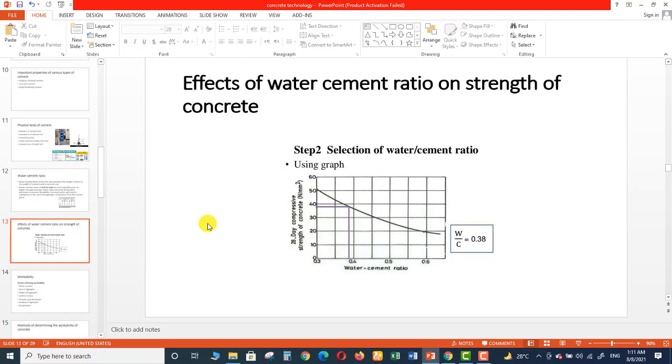As we previously discussed, that is the same thing. According to the water cement ratio law, the strength of concrete only depends upon the quantity of water used in workable concrete mix and is quite independent of the proportion of cement and aggregate. There is a law which we call the water cement ratio law, which was introduced by Abrams in 1918. That law says that with given concrete material and conditions of test, the quantity of mixing water used per bag of cement determines the strength of concrete, so long as the mix is of workable plasticity.